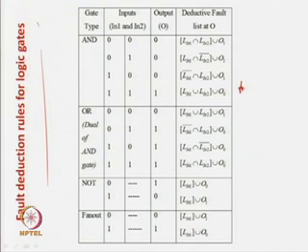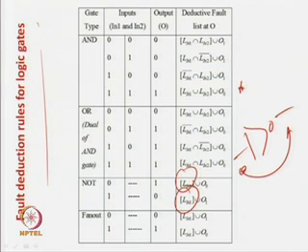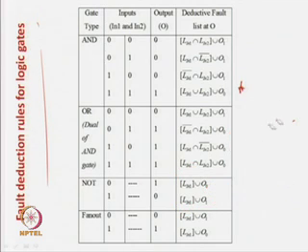For the NOT gate, we know that whatever is in the input of the NOT gate will be propagated. So, it is an inverter. Whatever is here is automatically propagated here, but if the input is a 0 over here, we get the answer 1 over here. So, a stuck-at-0 fault is detected. If it is a 1 over here, the answer is a 0 over here, and a stuck-at-1 fault is detected. That is what is stored. And in case of fan out, it is the same thing as an inverter.